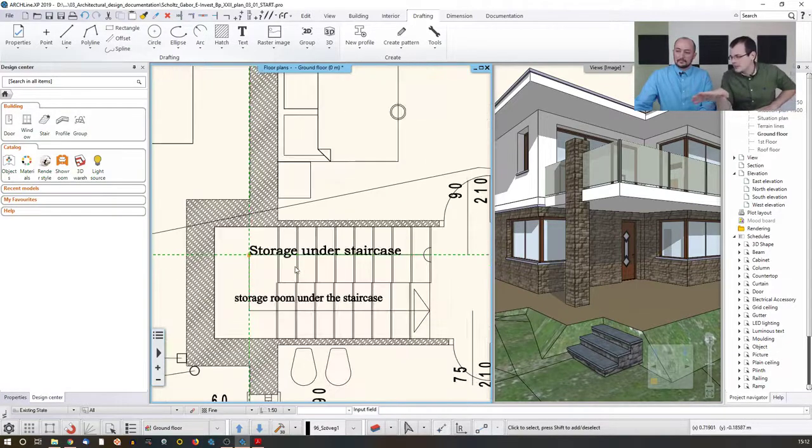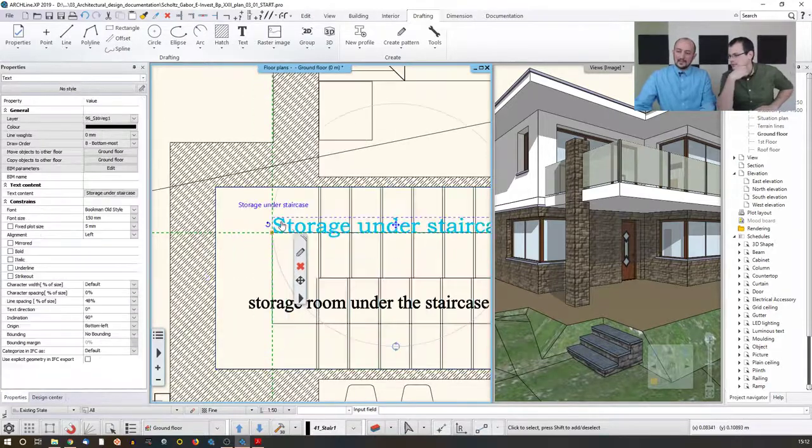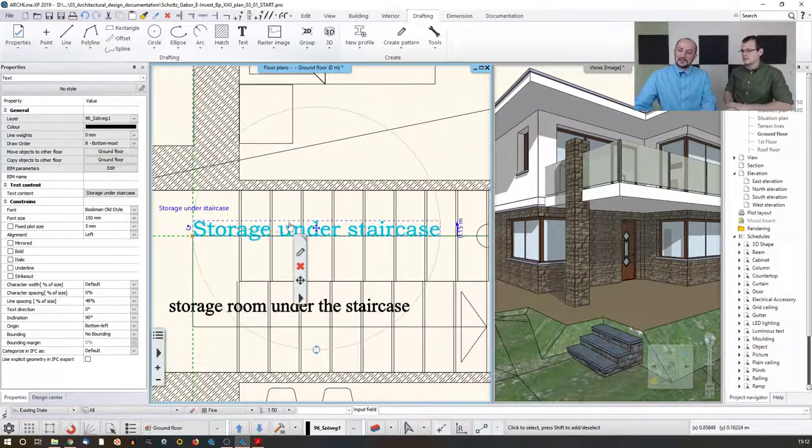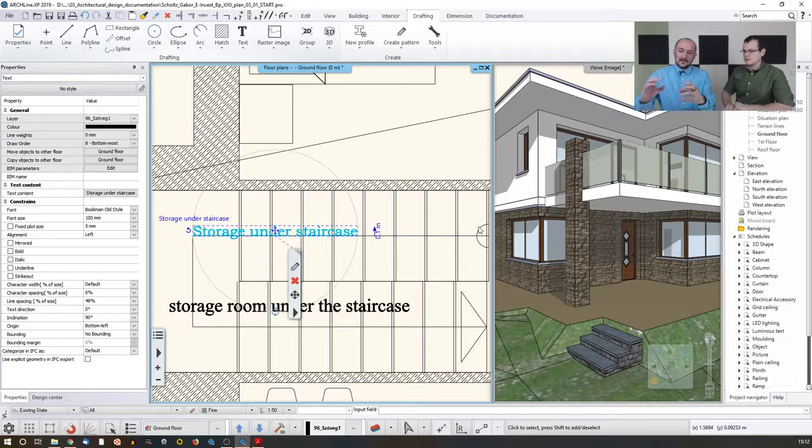I actually have something like that here, so you can just place it over there. It's very good that this came up, because now you see that the font size is different between the two text fields. So how do you amend that? Well, there are two ways to do that. First things first, you can click on that and you can see the size of the text. So you can change it, let's just change it to 10 centimeters. Yes, see, this way you can change the size of the text. You can make it larger, you can make it smaller. Actually, this changes this value here, fairly similar to how you would change the thickness of the wall or the height of the wall. All the rest of the properties are here at the left-hand side.